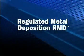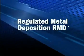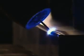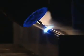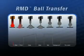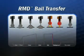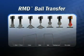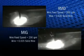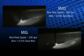Regulated metal deposition, or RMD, is an optional software-based, precise wave-controlled short-circuit transfer and eliminates spatter. It's a method of predicting when the short is going to clear and then rapidly reacting to this data, changing the current levels. Early prediction of the short clearing enables quick reduction of the available current, minimizing the arc force and reducing the amount and size of spatter. The molten puddle is calm, reducing splash and cold lap effects normally associated with short-circuit transfer.